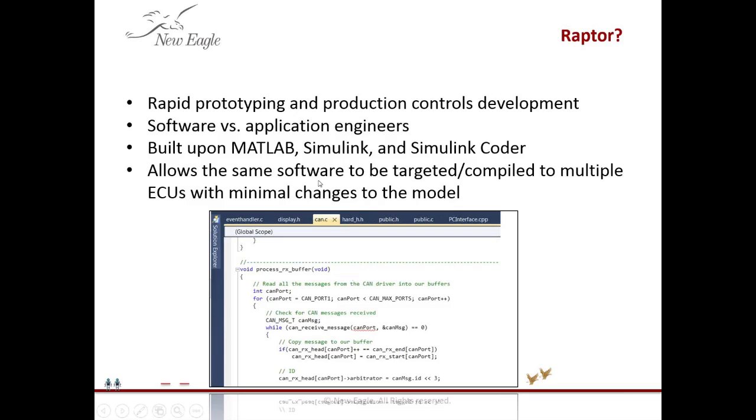And actually in some cases, like with the vCAN 320 and the vCAN 800 that have some I/O, for simple applications, the display can actually take the place of both the display and an embedded controller using the CAN and the analog inputs and digital inputs and then the outputs to do actual control functions. And you can put control logic in Simulink and Stateflow, and that can take the place of an embedded controller in some systems.